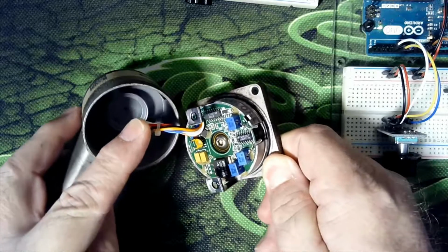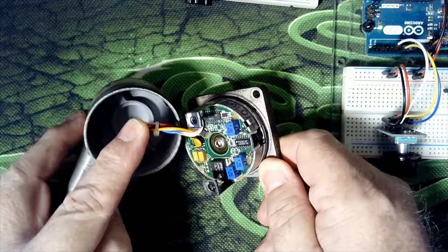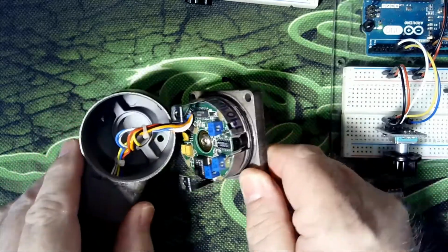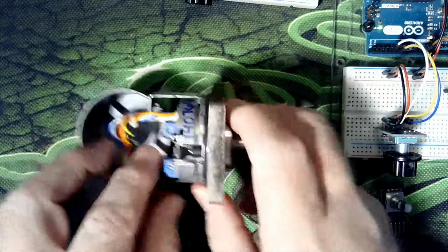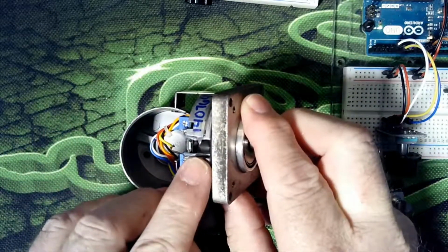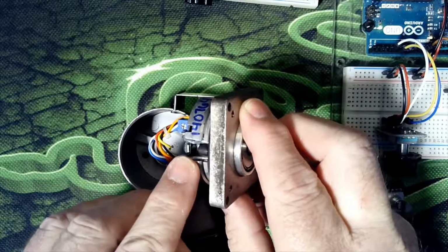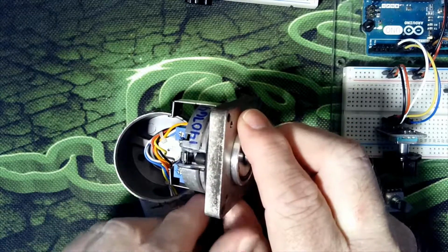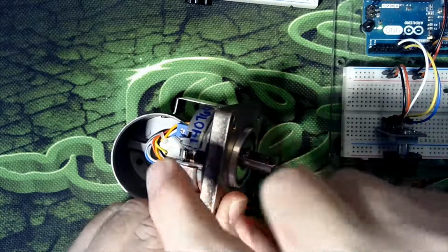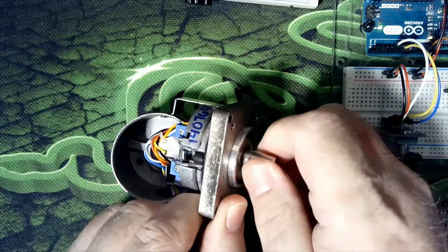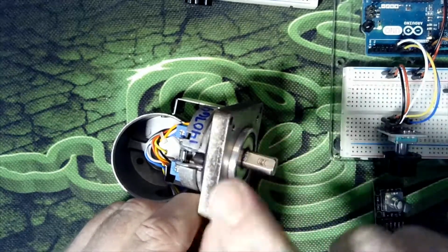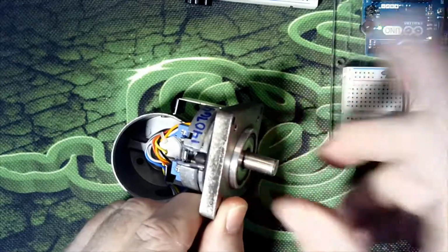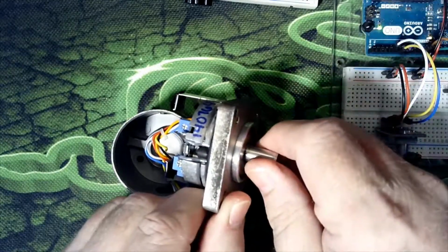Now this one takes 24 volts coming in to run the circuit board, and then everything else is done on the board. What's hard to see is where this emitter is in here. There's a dark piece of material here, and on that is a bunch of slits which the light passes through. And in behind it, when I turn this shaft, there's a disc with all kinds of holes in it, and I'll kind of represent that with one of my drawings here so you can see it.